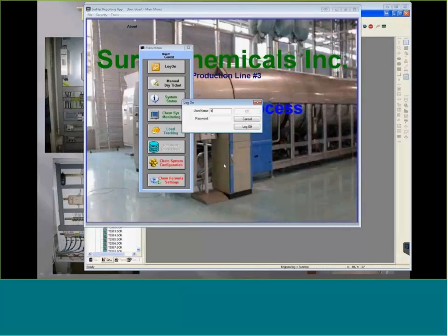What happened here was it logged me out. That's why it wasn't giving me access to those buttons. And that's another great thing with InduSoft, the ability to protect or lock out certain areas or buttons, or access for different levels or groups of people. It's so easy to do that you need to utilize it, because if you're not, you could be spending more time doing it the long way or the hard way.